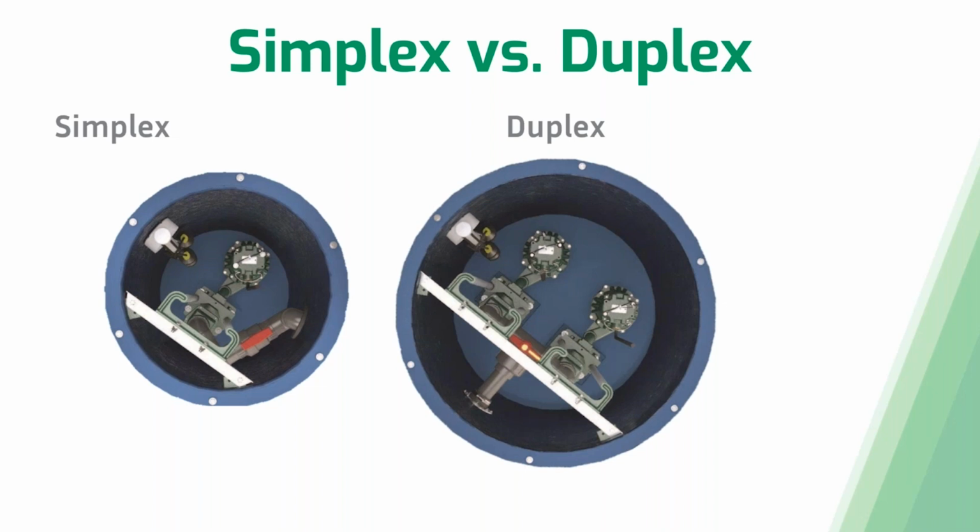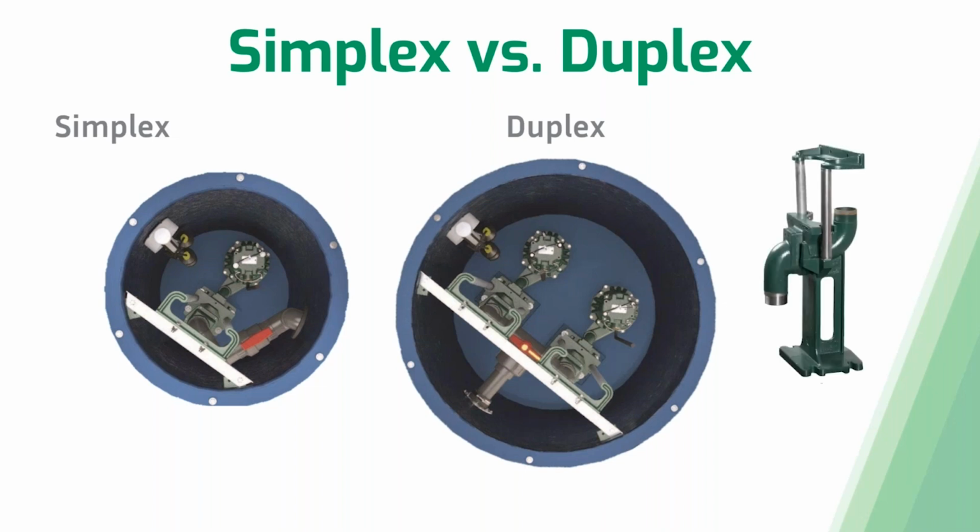And also, if one pump does end up failing, you have that second pump to keep the system in operation while you get that first pump serviced. Now when it comes to duplex systems, I'm typically going to always recommend using a rail system if it's non-automatic, whereas if it's an automatic system like in a smaller residential system, you can typically get away with two automatic pumps with a residential alternator.